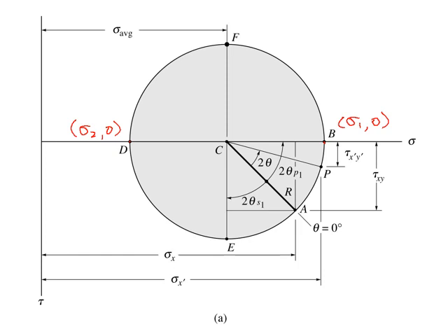And then we have E. E is the maximum value for shear. Coordinate is sigma average, tau max. And F is the other location of the plane where you have the maximum shear stress. So the coordinate is still sigma average but minus tau max.